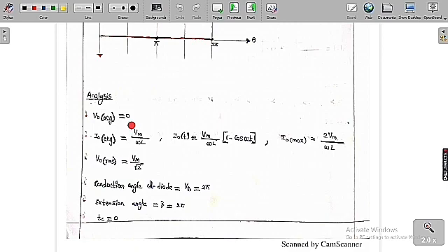So always listen carefully: the average voltage across an inductor is always equal to 0, and the average value of the capacitor current is always equal to 0. Listen carefully, the average value of the voltage across the inductor is always equal to 0, and also the average value of the capacitor current is always equal to 0. And also here, I naught average is equal to...